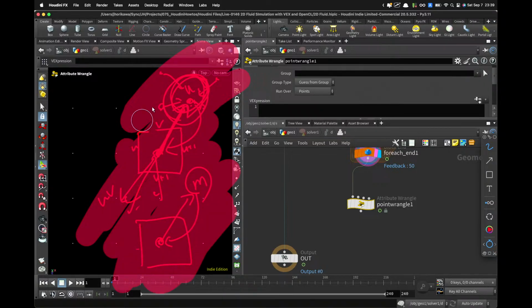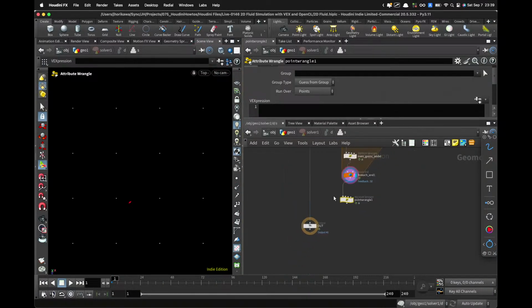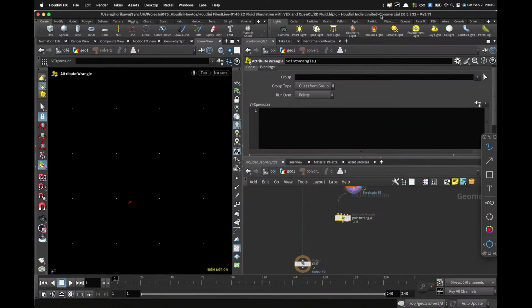So let's do that. I'm going to make it simple using the point wrangle, I mean VEX functions, to do this, rather than working on a bunch of arrays in a difficult way. So the functions that I'm going to use are pcopen and pcfilter to get the average value in specific directions, specific positions.